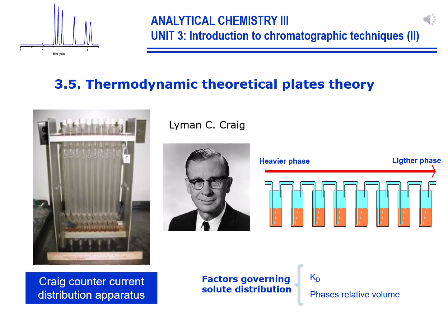Lyman C. Craig used this theory for fractionating liquid-liquid extraction. Counter-current distribution is a separation process that is founded on the principles of liquid-liquid extraction, where a chemical compound is distributed or partitioned between two immiscible liquid phases, oil and water for example, according to its relative solubility in the two phases. The Craig counter-current distribution apparatus is shown in the picture.